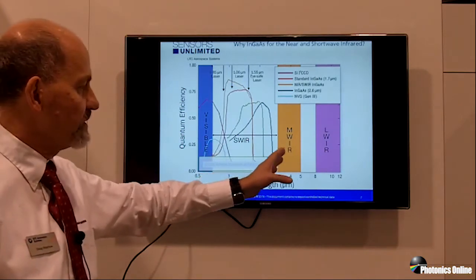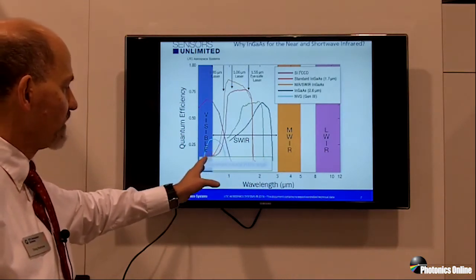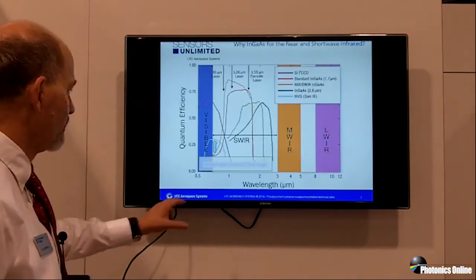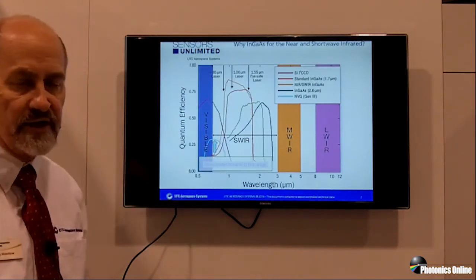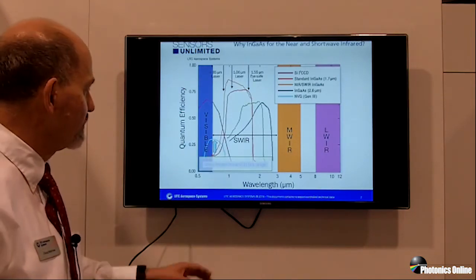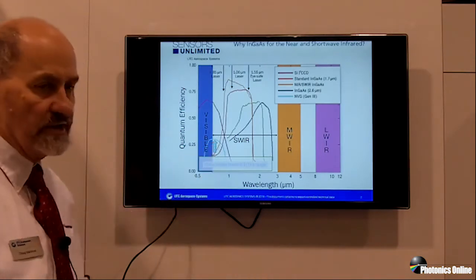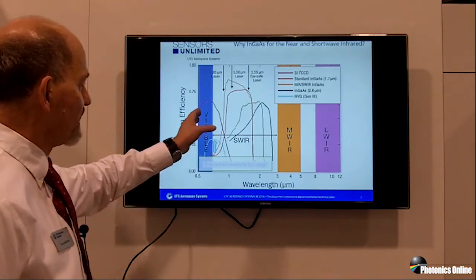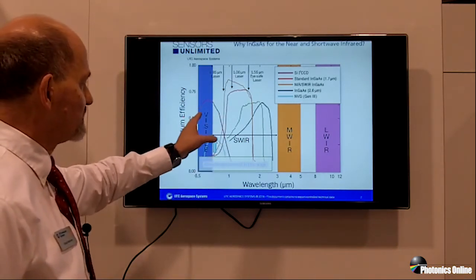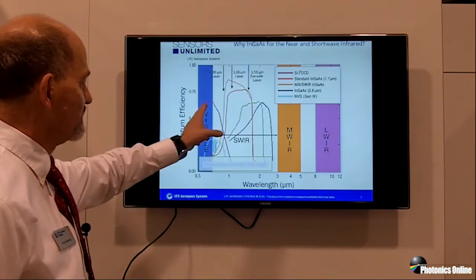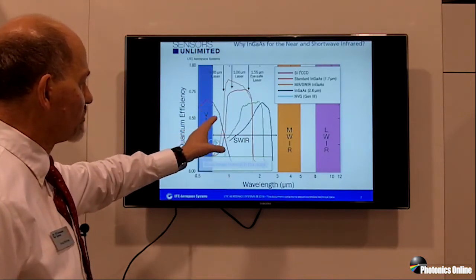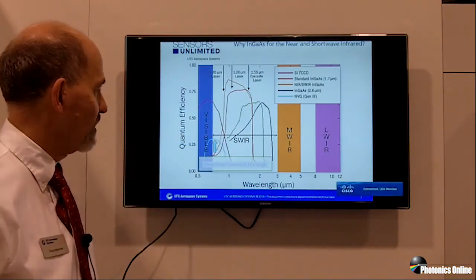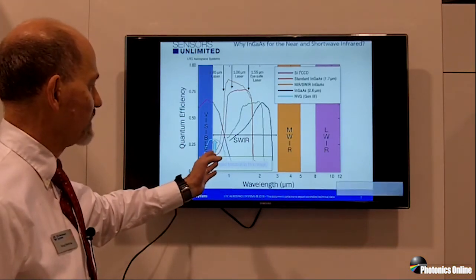And we have various detector technologies illustrated, starting with this blue curve, an intensified photocathode tube. It's got low quantum efficiency, but it is very sensitive because it has large amplification. Your standard back-thinned CCD has a response like this. Middle percentage range, folds over, starts dropping because silicon becomes transparent at longer wavelengths and is actually used as windows.